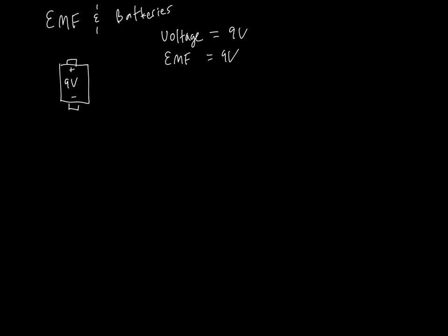So people will use the word voltage and EMF interchangeably. And if you took this battery and connected it to an ideal voltmeter, such that it has an infinite impedance, therefore it draws no current from your battery, the voltmeter would read 9 volts.